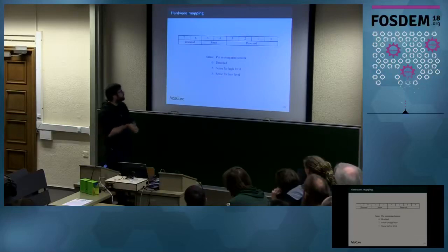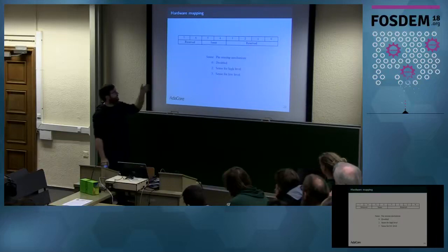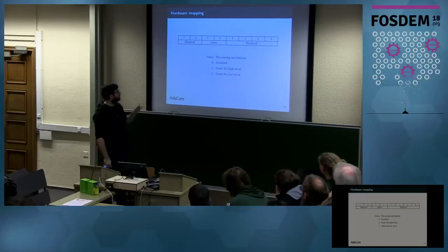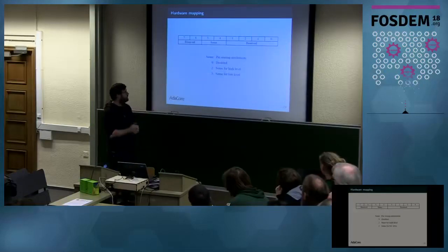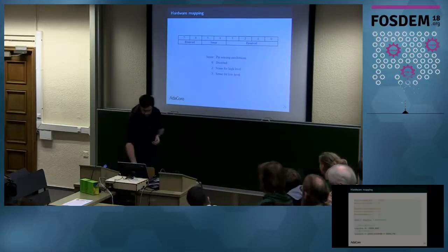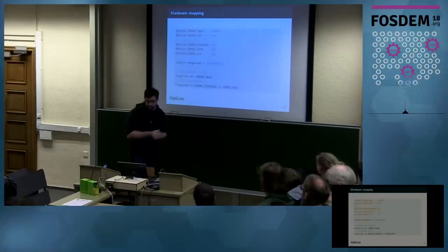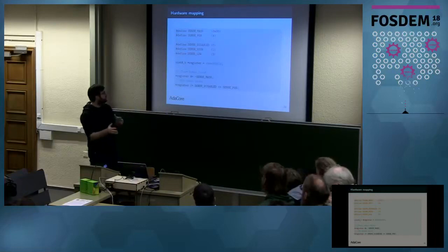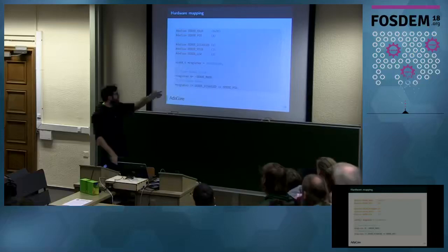So here we have what is called a memory mapped register. It's 8 bits, and we can see that there are some fields inside those 8 bits that are defined. The first 4 bits are reserved, they are not used. The 4th and 5th are used for the sense field, and the 6 and 7 are not used as well. The documentation will tell us what the possible values are and the meaning of those values for the sense field. In C, usually you will have drivers written with something like that. You will make more or less macros and bit shifts and masks, like you see here.